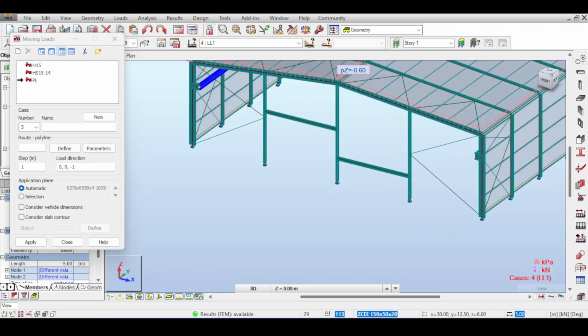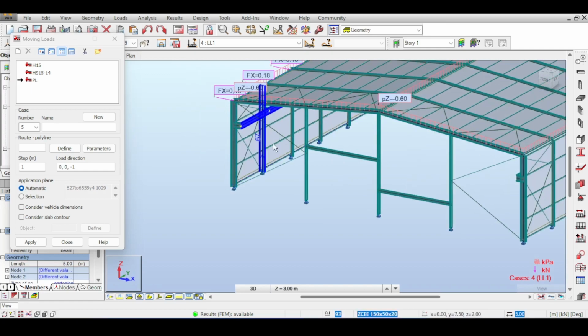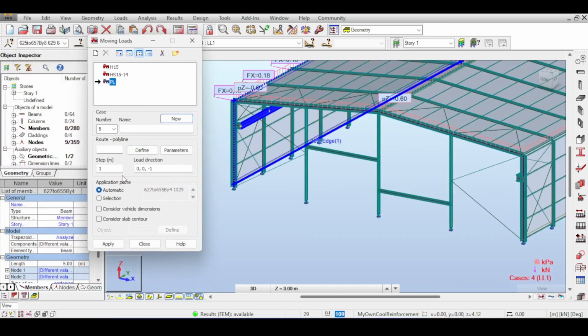The second issue I wanted to talk about is also a comment from audio subscribers explaining that you could also model not only the crane load, but also the crane acceleration, stopping and accelerating, which is a horizontal force, by simply adding here a factor. Like if you calculate and realize that the equivalent horizontal force for the crane accelerating and decelerating is like 0.5 of the vertical load, you just put here 0.5 and you're golden. Everything will be working perfectly fine. Of course, we had a different factor here.